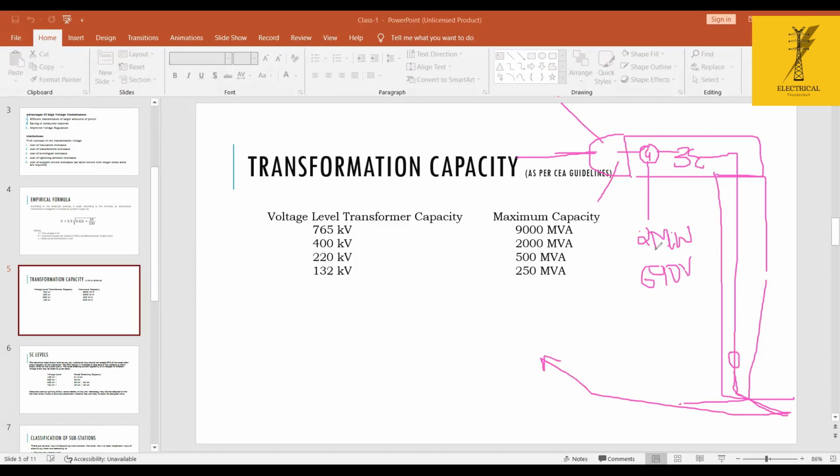So each turbine is generating 2 megawatt at 33 kV voltage. So for our 200 megawatt, we have to install 100 wind turbines. All these wind turbines are connected and pooled at one location, where the 33 kV has to be stepped up to 220 kV, and that 220 kV you are exporting to the grid. Where the stepping up process is going on, I am calling it a step up substation, where the transformation of the voltage is happening, which is stepping up the power from the low voltage to the high voltage.